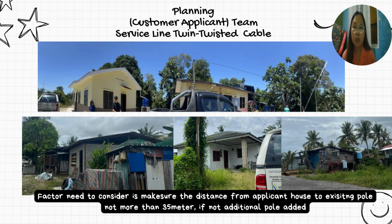Next, I also joined the customer applicant team. As you can see in the picture, the size of the house is small, so the suitable service line for this full house is TT cable, which is twin twisted cable. Another factor to consider during this site visit is to make sure the distance from the applicant house to the existing pole is not more than 35 meter. If not, an additional pole will be erected.